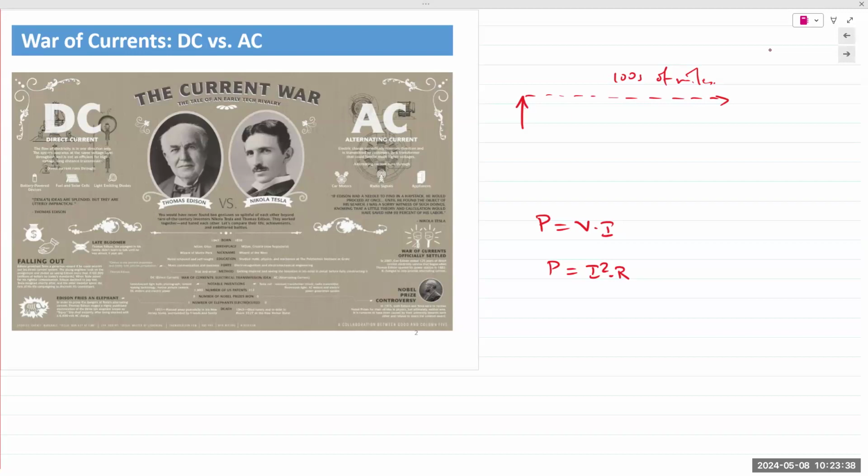So people were apprehensive. Instead of choosing a higher number, they chose a nice round safe number of 100. And they built a 10% tolerance into it. So it became 110. And then once the infrastructure is set up, you can't change the entire infrastructure. So it's between 110 to 120 volts. The rest of the world followed shortly thereafter, but instead of sticking with 100 volts, they stepped it up to about 220 to 240. Yeah, that's the reason. So you can give more power without increasing the current.